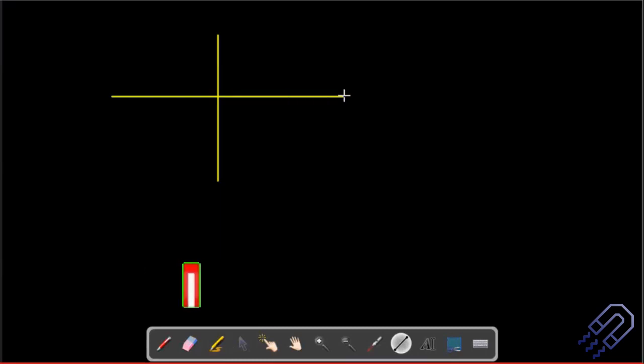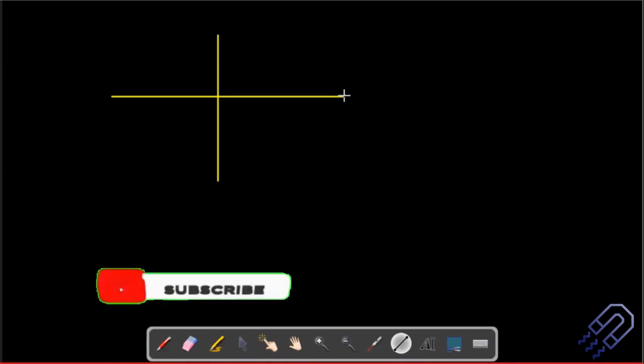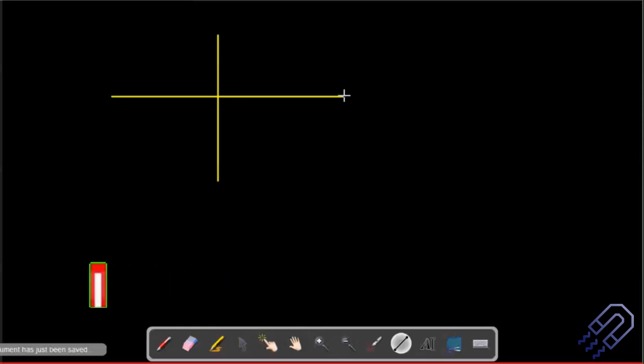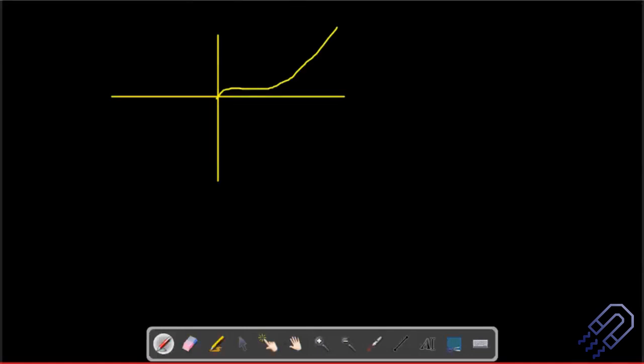Since we are using gallium arsenide, the values of the reverse voltage or the forward bias voltage might change a bit, but the behavior will remain the same. Only the current range and the voltage range will change. So you basically have a forward bias like this, and if we consider a reverse bias like this, this is your Zener breakdown or avalanche region. These regions will still be there. It's not that this region will only be there for a Zener diode; it depends on any kind of diode.